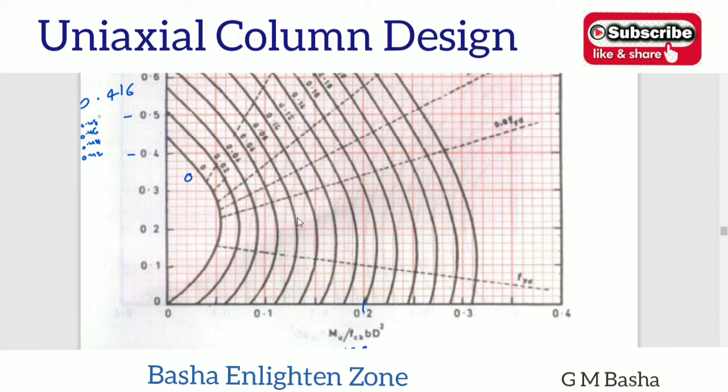So according to that only I am seeing here, 0.138 means 0.1, 1, 2, 3 and 4. So your value lies between 0.13 and 0.14, means somewhere here. And again this 0.416 will be between 0.4 and 0.42, somewhere here like that. Okay, so if you relate these two things, it is better on paper to keep some scale and draw a line like this and draw a line perpendicularly to this value. Then wherever it relates, take down that value.